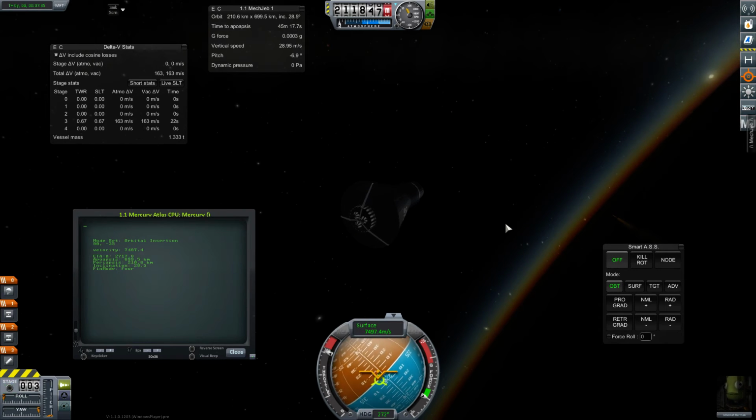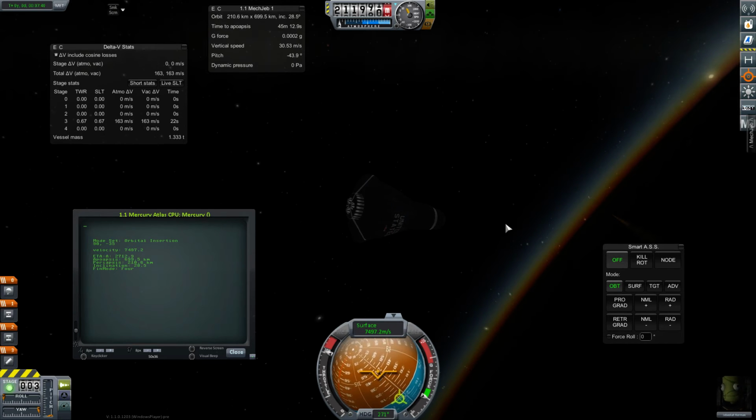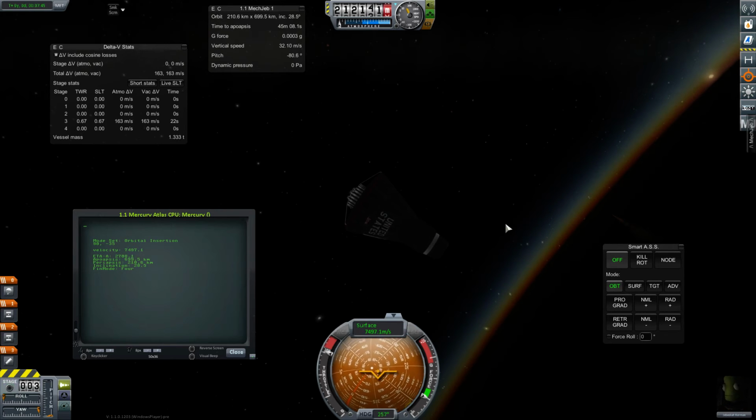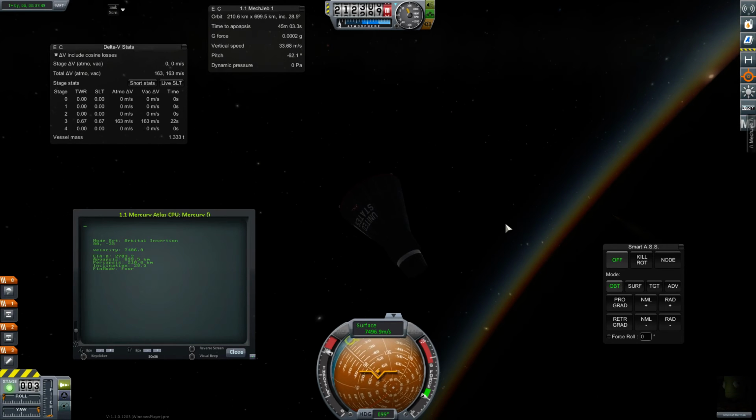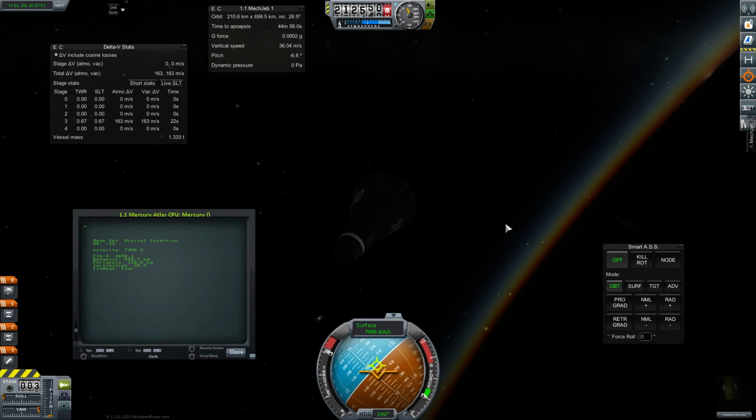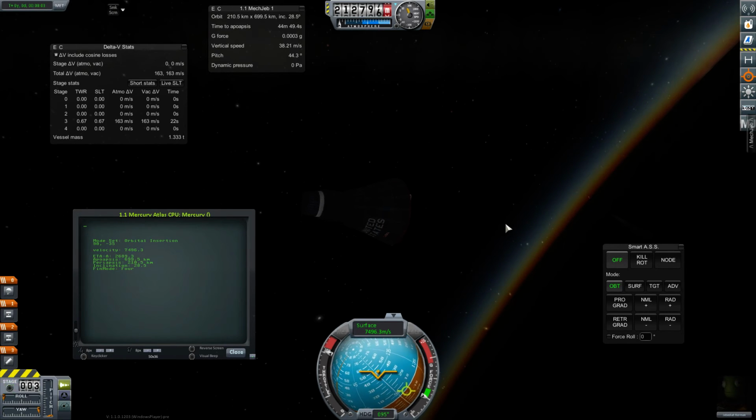I want those to be continuous functions. So pitch is the output, and all those other factors go in as linear inputs. So it's fed the speed, it's fed time to apoapsis, whatever other values I can derive, and it outputs that pitch. So the pitch won't only be -5 or only be 0. If it finds, okay, it doesn't need to be -5 anymore, it'll come up with a desired pitch that is between -5 and 0. There might be unintended consequences of that. I haven't set up the program to do it yet, of course.